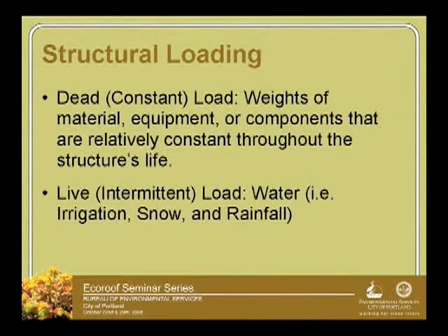So just in structural loading terms, there's really two major categories when we're talking about weight. One of those is dead loads, or constant loads that are on a building. And those are weights, materials, equipment, or components that are relatively constant throughout the structure's life. So HVAC equipment, the membrane, pavers that might be up there, a gravel ballast system that might be up there in order to hold down